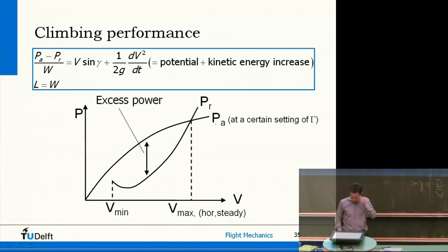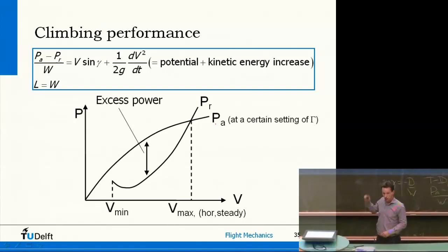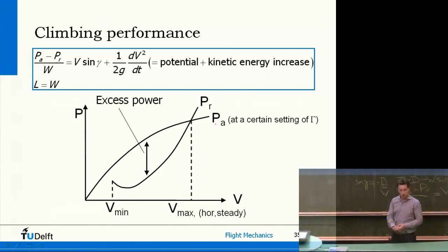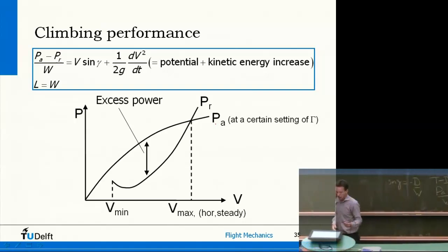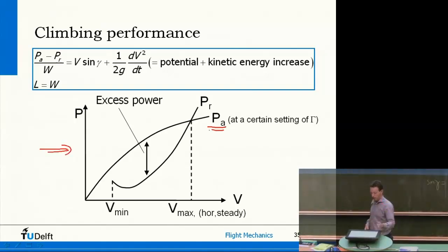So, okay. In general, this was the picture we have. So we have a power equation, and what I've drawn over here is a very general performance diagram. Now, we're making these assumptions about jet aircraft, about propeller aircraft. In real life, there aren't nice straight lines. It could be anything in between. This could, for example, be a turbofan engine, which behaves a little bit differently. So this power available curve can look like anything basically, but it will always start at zero because you have zero velocity there.